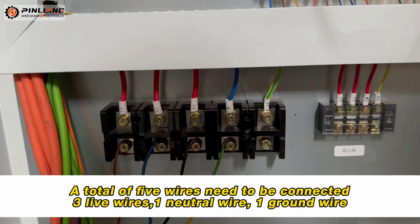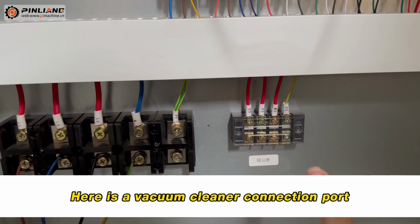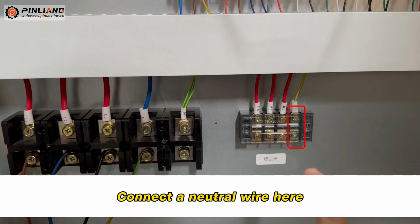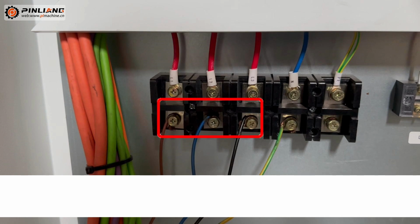A total of 5 wires need to be connected: 3 line wires, 1 neutral wire, 1 ground wire. Here is the vacuum cleaner connection part. Connect 3 live wires here. Connect a neutral wire here. If the screen cannot light up, please adjust any 2 live wires until the screen lights up.